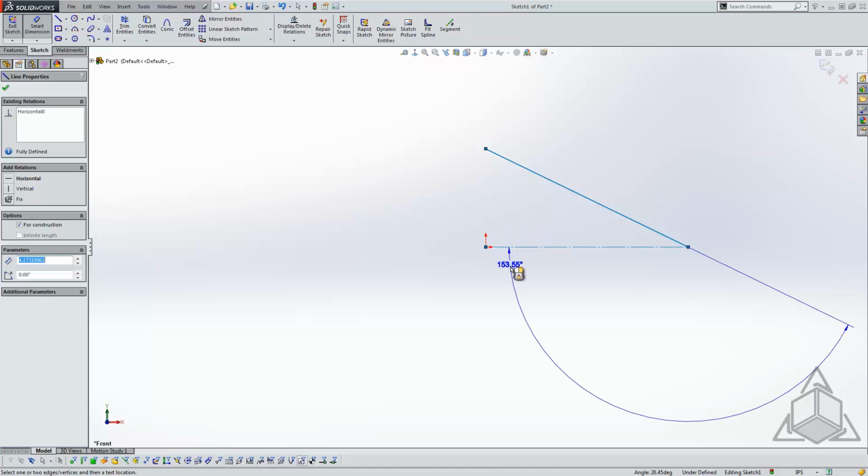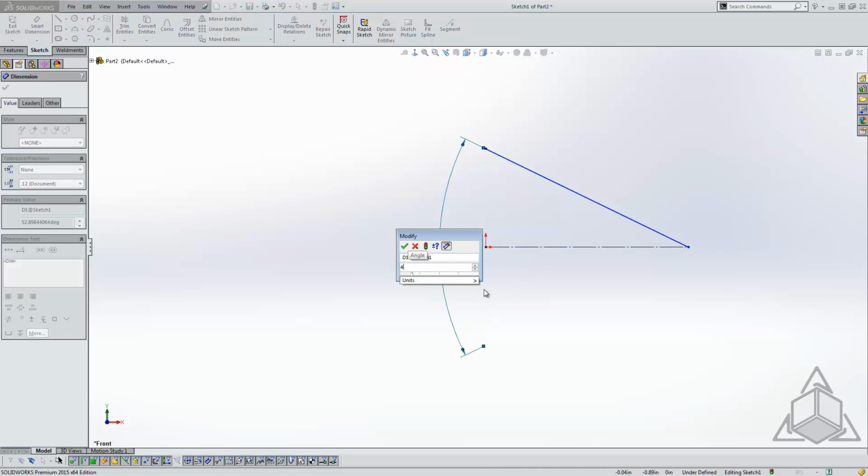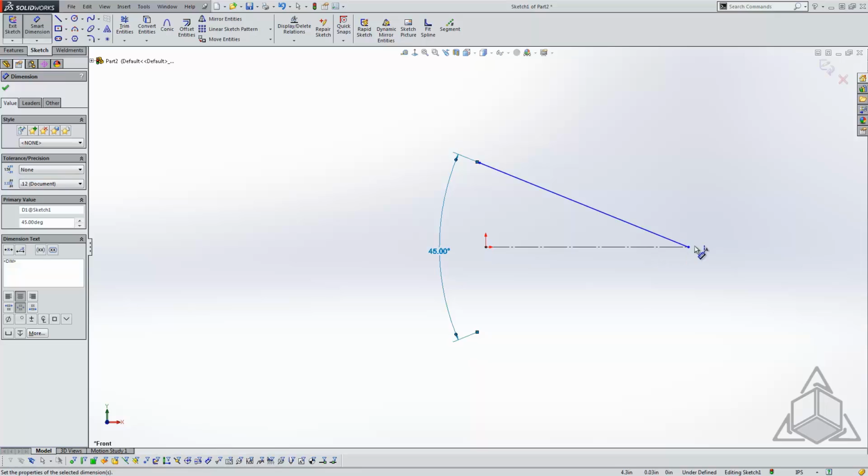And they did change that for 2015. It's a sneaky change that they made this year, because we do have to have a keyboard modifier, since we do need access to this angle sometimes. But if we hold our shift key, that modifies the behavior. So once we cross over, just like a diameter dimension does now, the double diameter dimension, we now have the ability to do that with angles, and this has been awesome. I've used this several times in setting up angle dimensions. We don't have to draw that other reference anymore. We can just hold shift and get that dimension out of it.